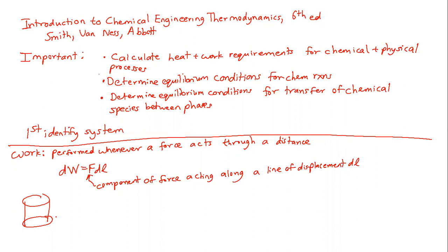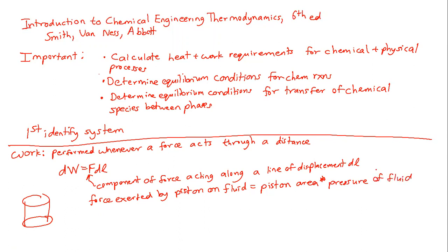The force exerted by the piston on the fluid equals the piston area times the pressure of the fluid in this scenario, and the displacement of the piston is the total volume change divided by the area of the piston.